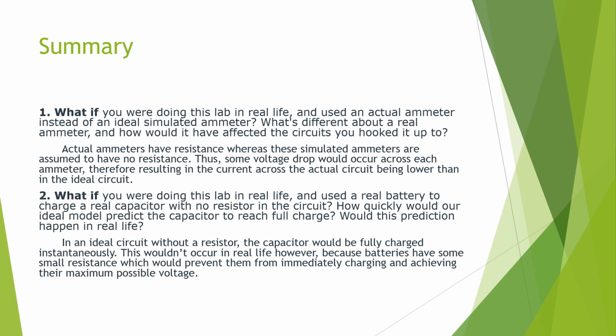Also, if a capacitor were charged in an ideal circuit without a resistor, then the charge would occur instantaneously. This wouldn't occur in real life, however, because batteries have some small resistance which would prevent them from immediately charging and achieving this maximum voltage.